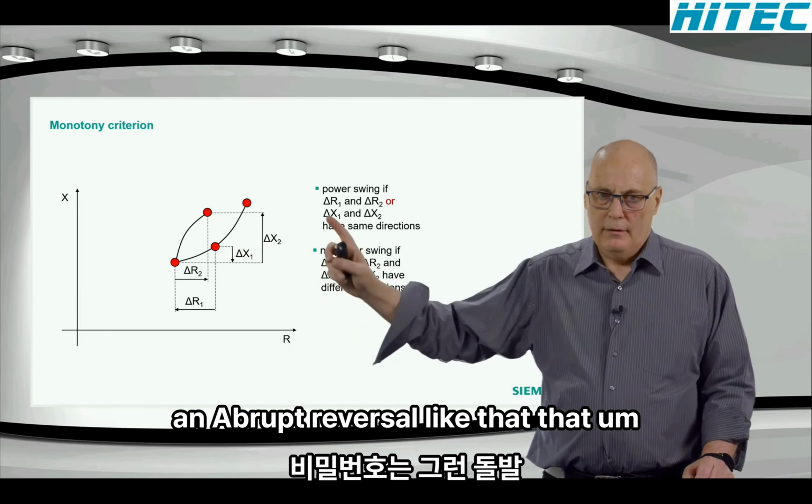That's just a note. Okay, in SIPROTEC 5, you will not see that gap that is shown here. In SIPROTEC 4, you did see this. So if you see this gap here, that is not relevant. The power swing blocking is still active there. In SIPROTEC 4, there was an 80 millisecond timer. What you see is the measurement drops off due to the jump, but there's a delay on reset of the function of 80 milliseconds, which bridges that drop off in SIPROTEC 4. In SIPROTEC 5, we changed the signal output. The signal output includes the stability timer, so you don't see the gap on SIPROTEC 5.